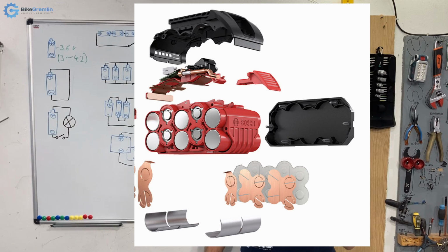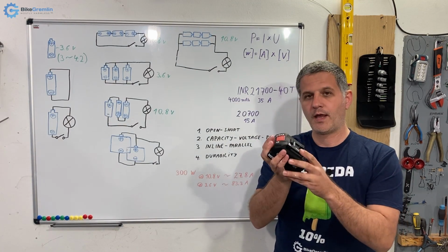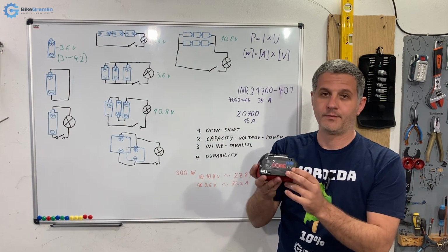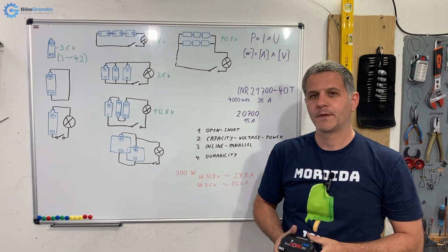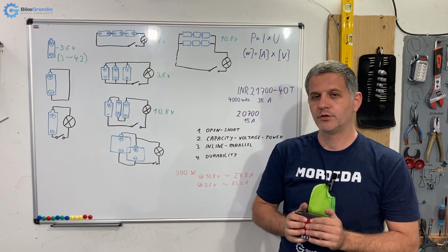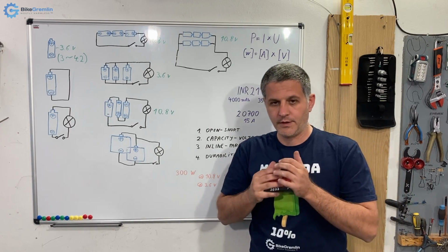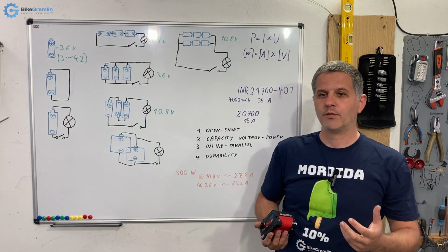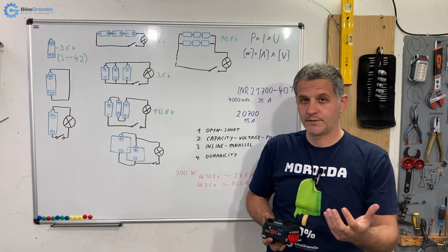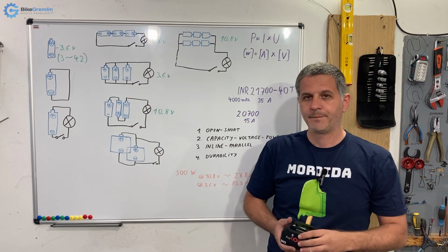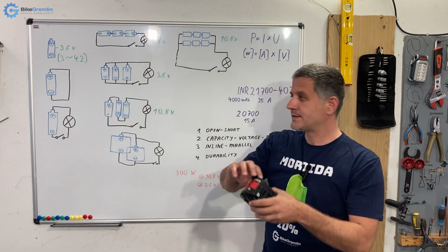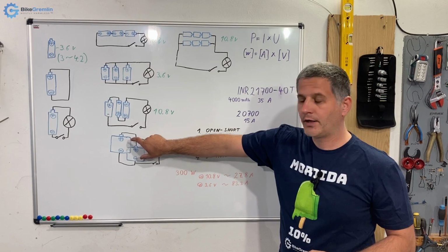That is also a reason why Bosch 8 and 12 ampere hour Pro Core batteries, for example, can give you more power, not just more capacity so that you can work for longer, but they will literally give your tool more power if it's a powerful tool that can use that power, because they have 2 sets connected in parallel.